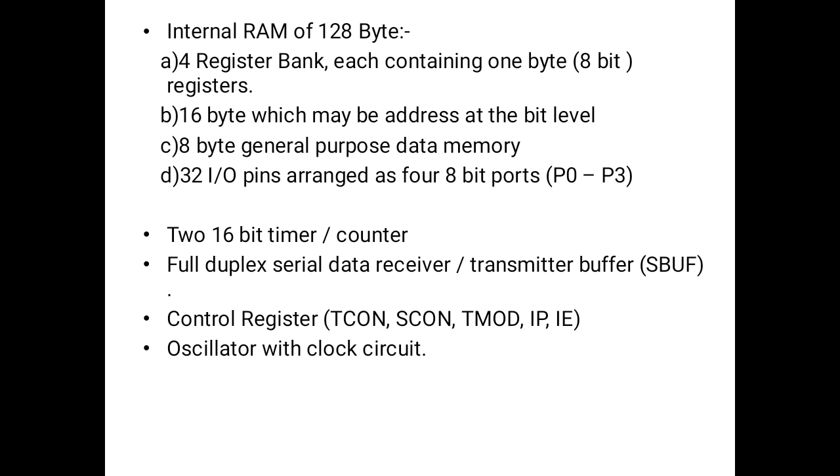Serial data communication is done through full duplex mode for receiver as well as transmitter, which is denoted as SBUF. There are control registers for controlling the timer and serial modes, denoted as TCON, which defines timer control, SCON defines serial control, TMOD defines timer modes, IP defines interrupt priority and IE defines interrupt enable. To provide the input clock, there is an oscillator clock circuit in the 8051 architecture.